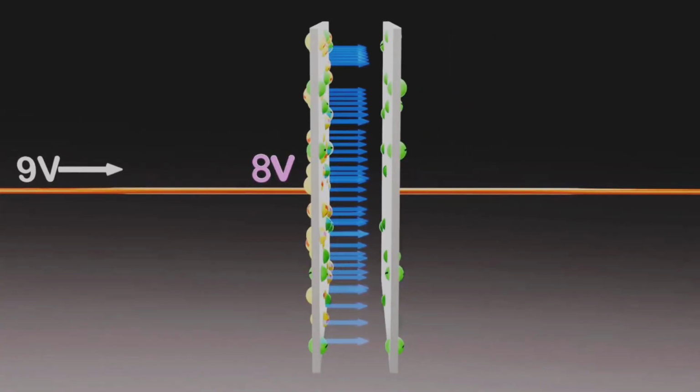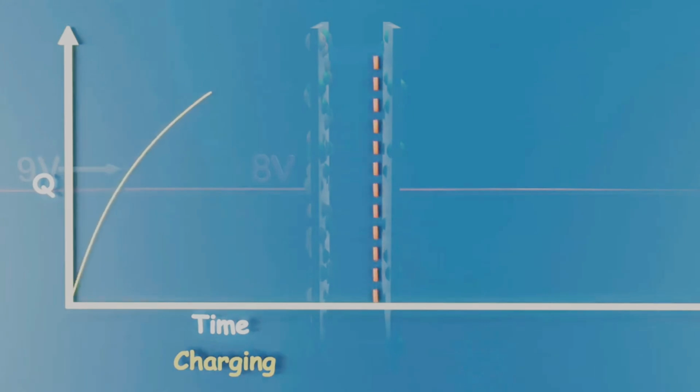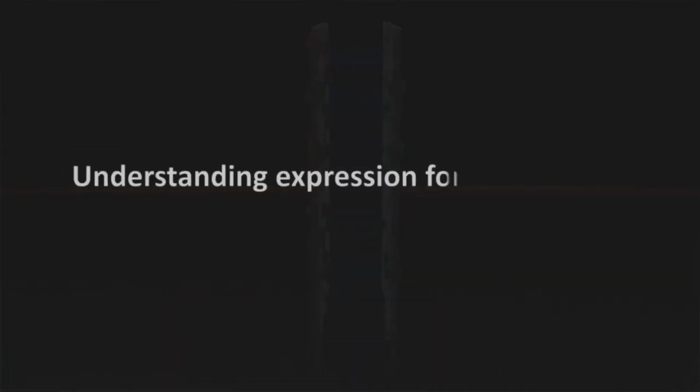For example, in audio systems, capacitors help remove high-frequency noise so that the sound becomes clearer. In radio and communication systems, they are used to control signal frequencies and improve signal quality. Fixed capacitors also play an essential role in timing circuits and oscillators. In combination with resistors, they can control the timing of electronic signals. This principle is used in devices such as timers, clocks, and microcontroller circuits.